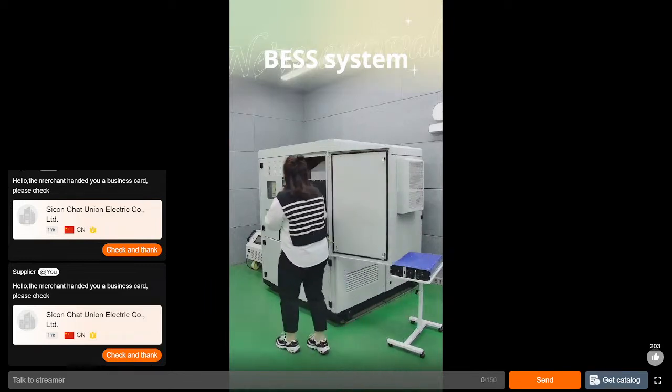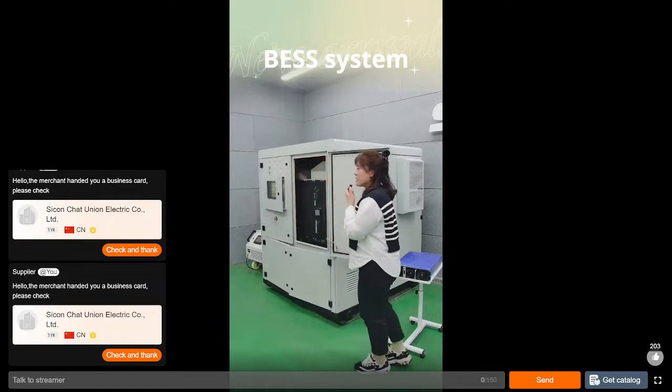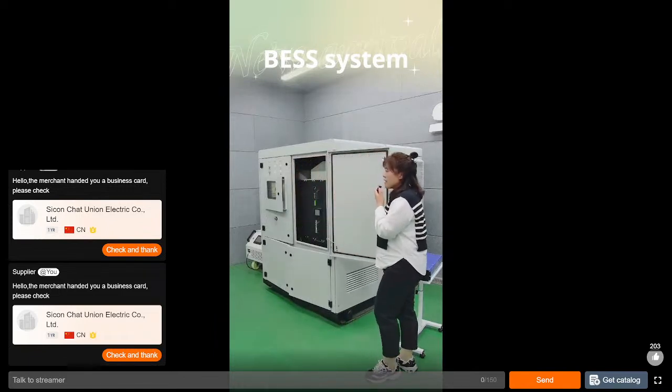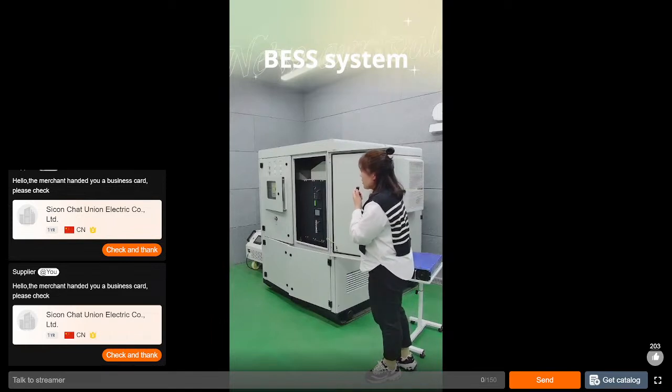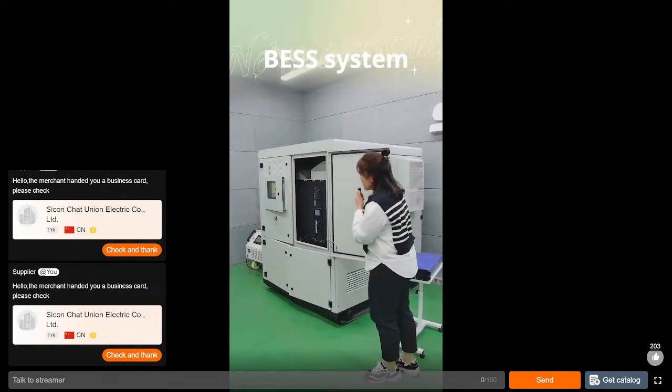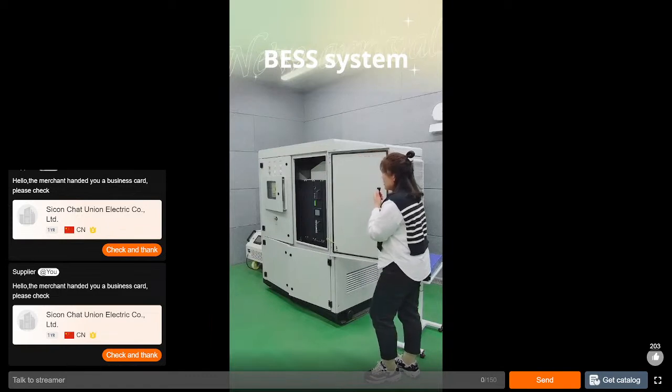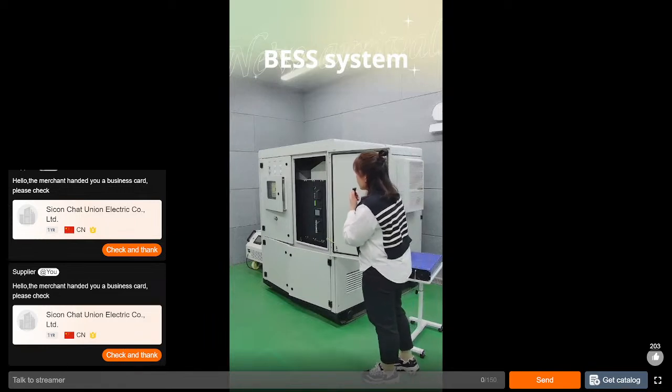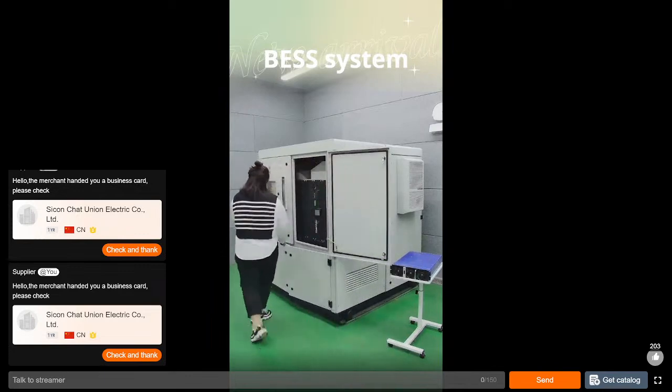And also inside the electrical cabinet, there is an STS module here. The STS is just like a breaker, a switcher. It will switch from on-grid to off-grid, and also from off-grid to on-grid. The main application of this STS is switching. The switch time from on to off grid is 15 milliseconds. Okay, for this part.